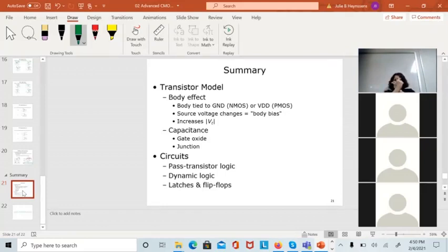Can you tell which is the drain, the gate, the source, and the body, looking at the picture and maybe the associated voltages? Can you calculate the current? Once you know the voltages, can you tell me what region of operation it's in? Then can you calculate the current based upon the region of operation? NMOS and PMOS region of operation.